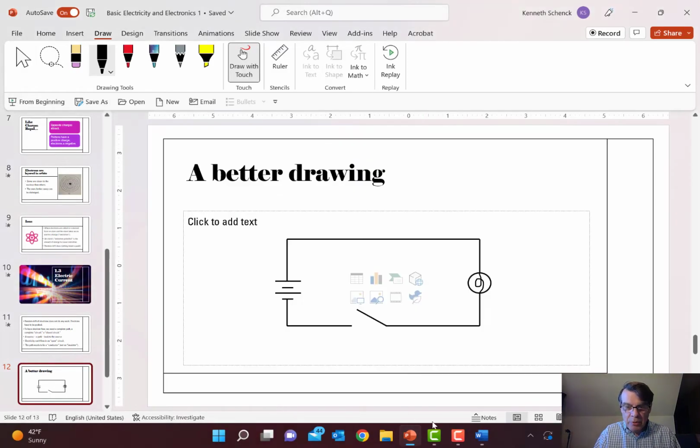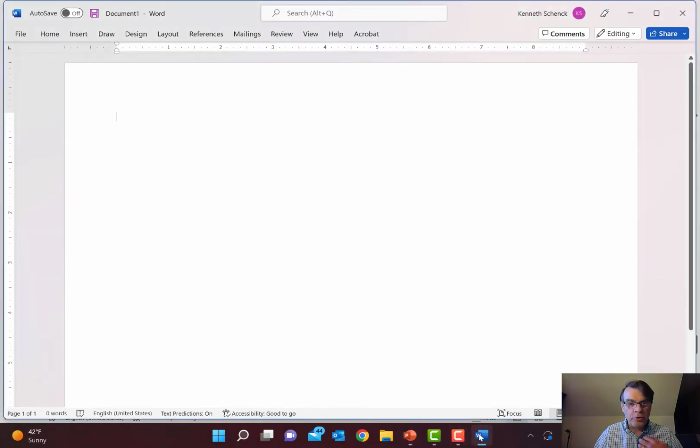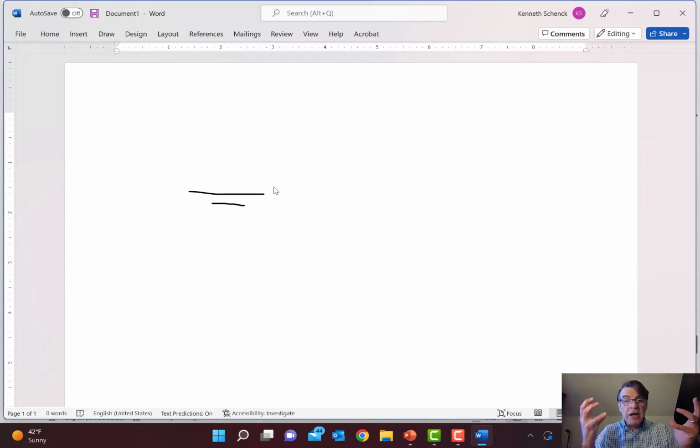Now, let me go ahead and I want to draw a circuit for you. So this is the symbol for a battery. This is one cell of a battery. Now you could multiply this. You could have more than one of these. You could have countless of these. But the smaller line represents what's called the negative terminal of the battery, and then the longer line represents the positive terminal of the battery. Now, we've got a pusher now. We've got a source of electricity. Batteries usually use chemical reactions in order to create a movement of electrons.